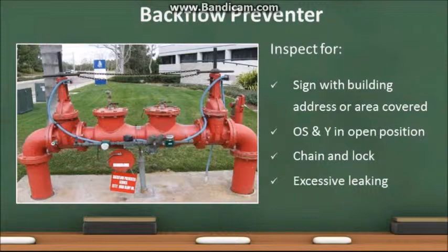When conducting an inspection, look for excessive corrosion anywhere on the valve. The tamper switch and conduit should be intact and without damage. Backflow preventers are equipped with fire department connections, also known as FDCs.